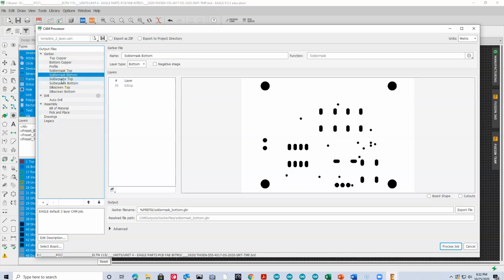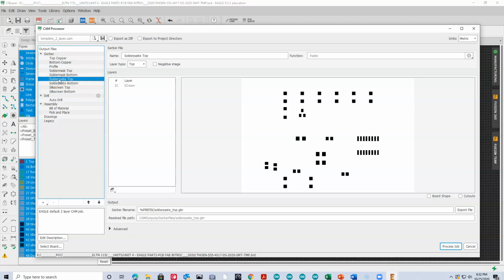Now, the thing that you're going to see here that's different is a selection called solder paste. And we'll talk about this a little bit more in the manufacturing process, but when we solder a surface mount board, it's very different than a through-hole board. You've soldered through-hole boards. That's what you did during the soldering week, where you soldered that little LED flasher. But in this case, it's soldered in a completely different way. This is basically a way of generating the tool, which is typically a piece of stainless steel, and where you see black, there are cutouts. And those are cut out with a laser, and so basically it creates a stencil.